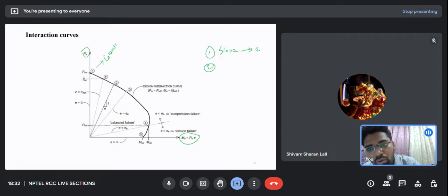And as we go below this curve, at point 1 dash, it corresponds to a structural component which will have axial load with some eccentricity. Let me classify it this way. Point 1 is where we take the eccentricity to be less than 0.05 d, and here the load carrying capacity is 0.4 fck plus 0.67, whatever it was.